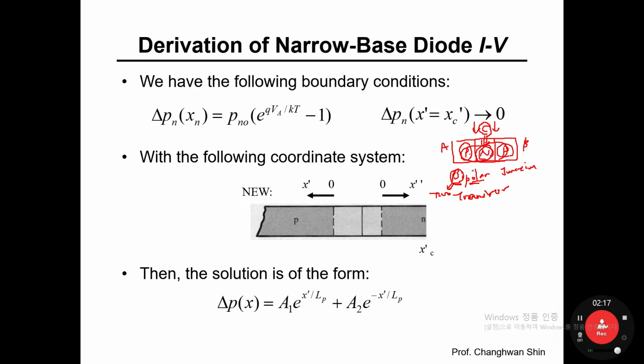Once holes are injected into the N side and diffuse towards the second junction, because of the internally developed built-in electric field in the PN junction, these holes arrive at the second P region. So we can say that the current is flowing from P to P through the N side.